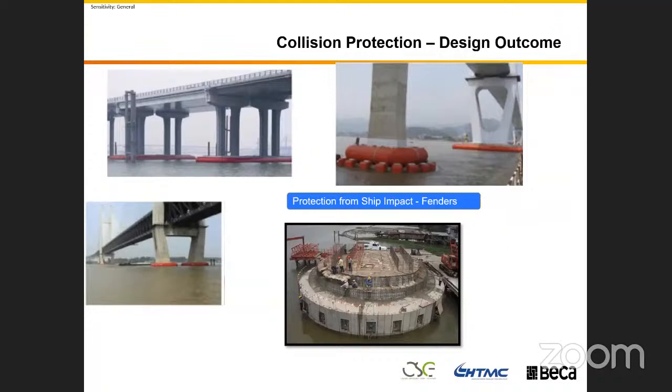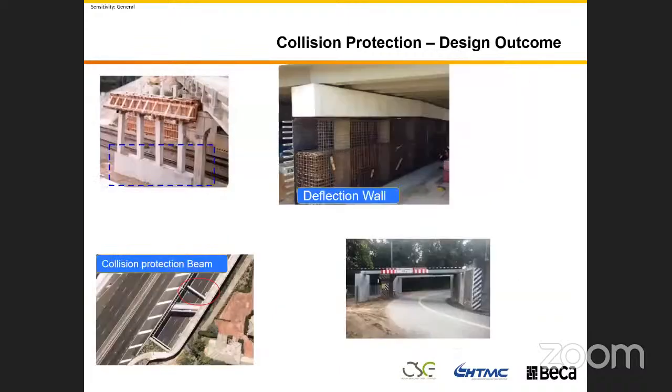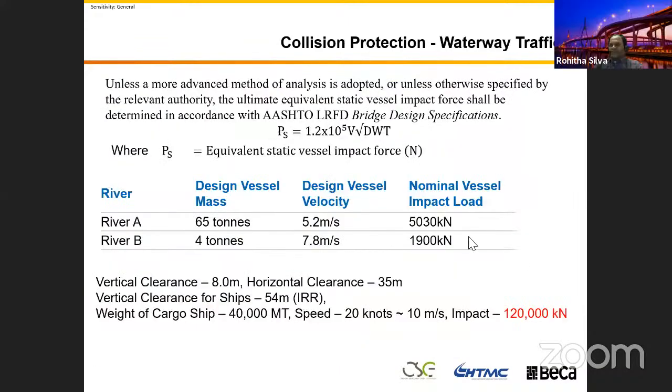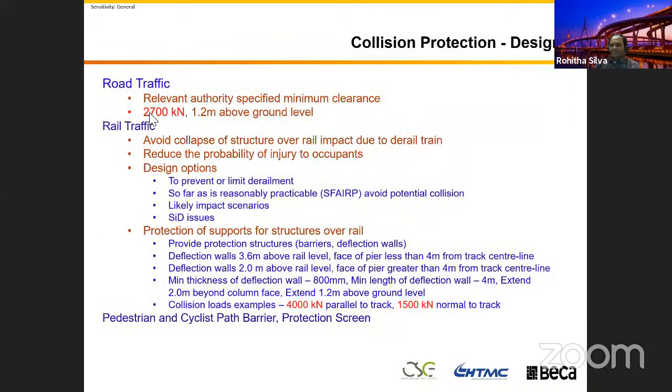Rohita, with respect to collision, how do you calculate these forces? Is there a standard? It's a bit of an arbitrary incident, no? And this one is actually based on a lot of testing. This 2,700 kilonewton is in the Australian standard, based on a lot of crash testing.